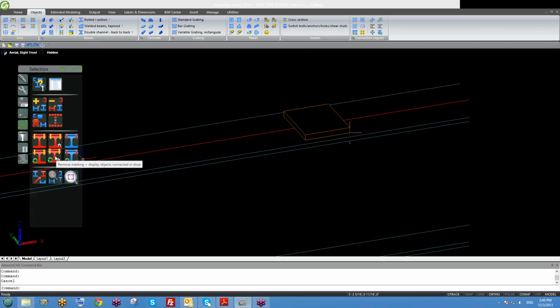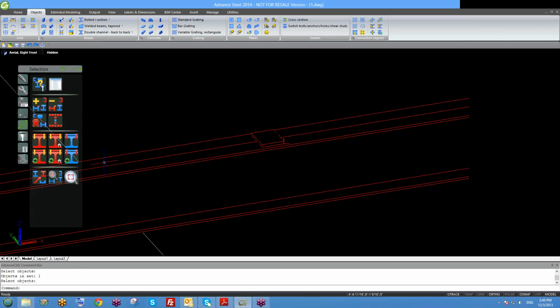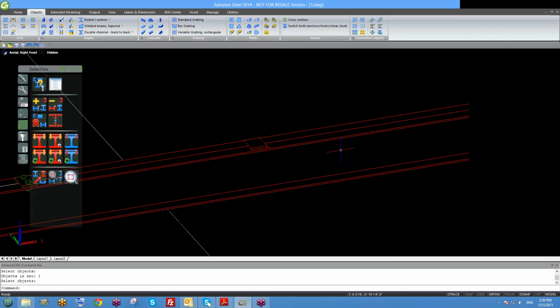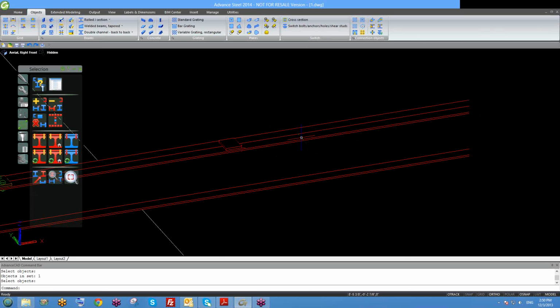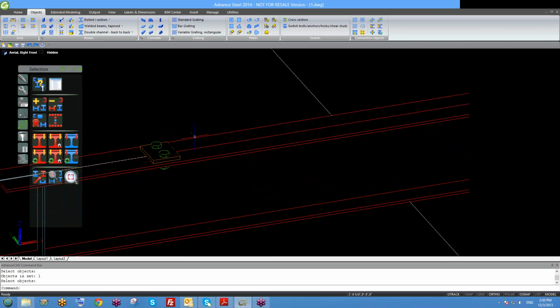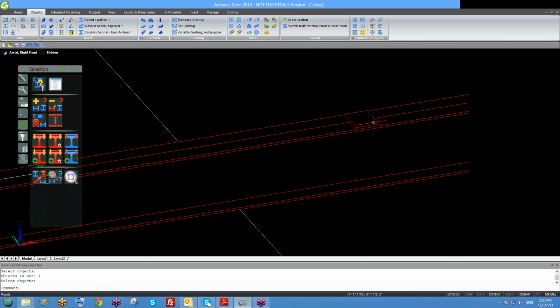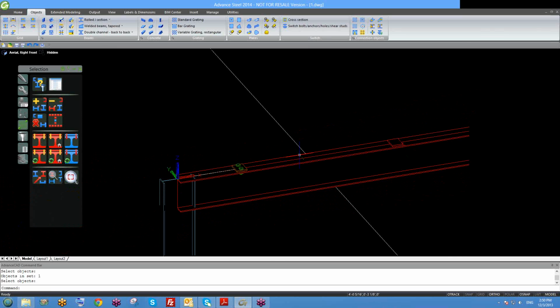We're going to see that tomorrow, but at the moment, just to show you how it works. When you select your assembly, your main part, whether it's a column or beam, it's going to highlight all the attached parts connected to that specific part. So in this case, you can see this plate is not part of my assembly, but this one is.